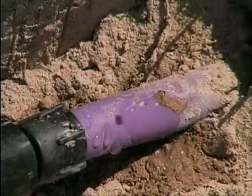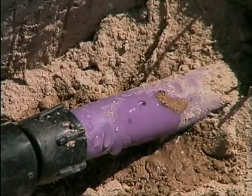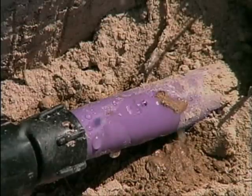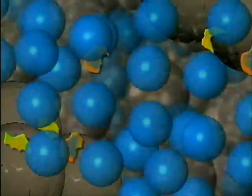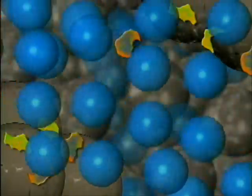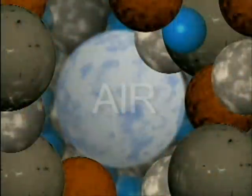This low flow rate, combined with a controlled dosing frequency and length, allows the wastewater to move through the smaller soil pores under unsaturated conditions. This movement through small soil pores allows remaining solids to be filtered out. It also allows organic matter and pathogens to be absorbed onto the biomass growing on soil particles.